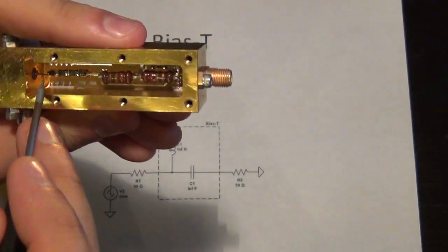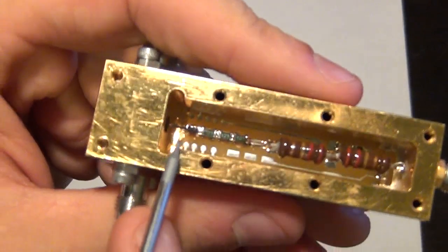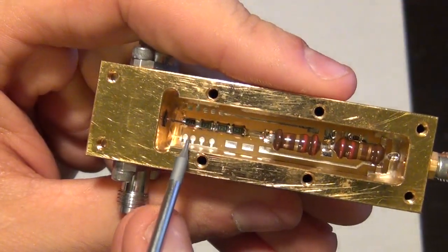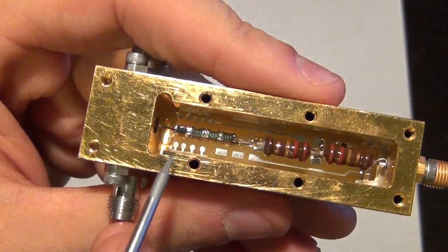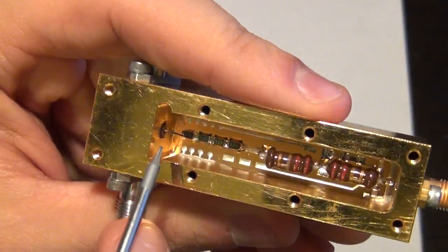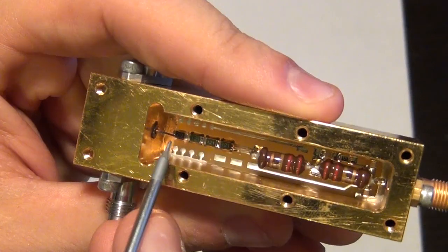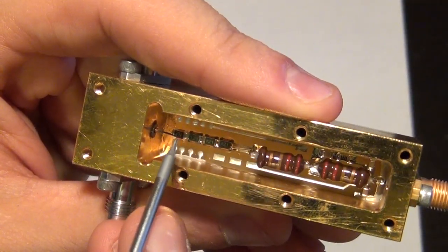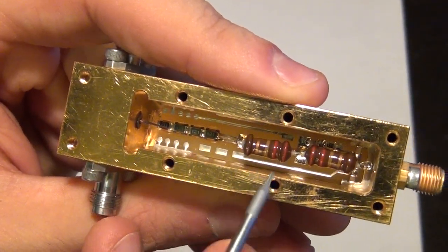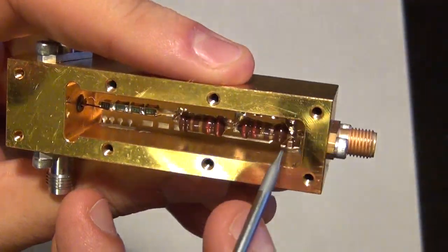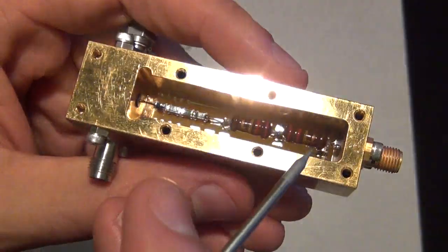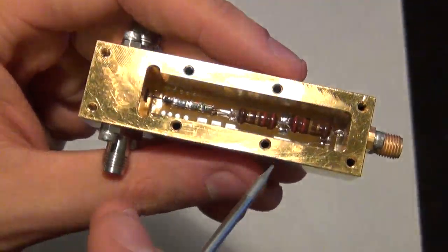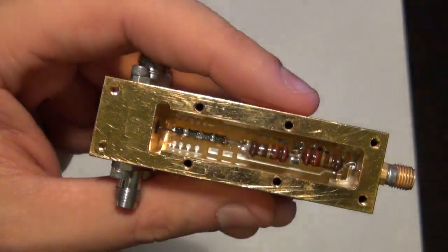You can see on top of every inductor there is a surface mount resistor that they have put there in order to DQ the inductor, make sure it has the proper frequency response and a proper damping factor and so on. And if you look very carefully, you can see there's a pin that comes out, and there's a tiny little wire that connects to the first inductor, and second one, third one, fourth one, fifth one, sixth one, and so on. And there's some more resistors and capacitors in there to decouple everything and make sure it works. So even a very simple bias T like this one is extremely complex inside and is handmade.